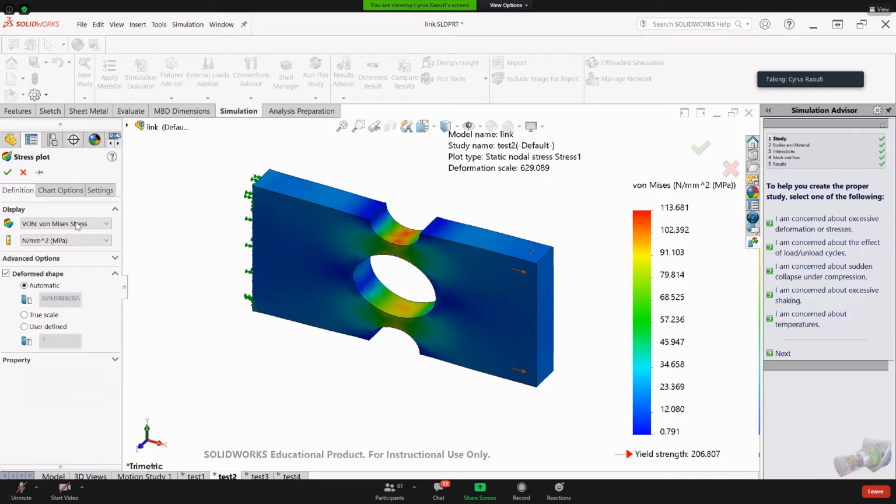Now, here we have normal stress. We can have shear stress. We can have principal stress. Remember principal stress, the maximal stress that you can find in an element, from your strength of materials course. You can plot those, and so on. There are lots of results here. Also, you can come here and have a tensor plot. If I say show as tensor plot,